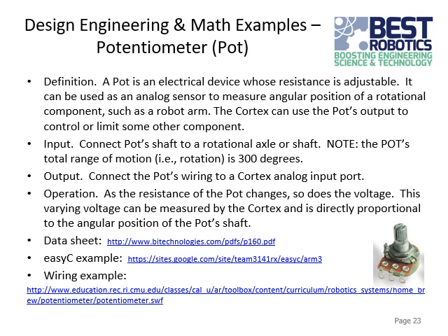It can also be useful if you want to automate some tasks so that a driver doesn't have to manually do it. So let's say you want to have a button that automatically rotates your arm 90 degrees. Well, if you have a potentiometer there that's connected to the axis, then you could see what the current angle is, and then take control of the motor and turn it until it gets to the new angle that you want, and then tell it to stop. Doing automated things like that can make the driving a lot easier for your drivers, and that can help you do better in the competition. It can make things quicker.